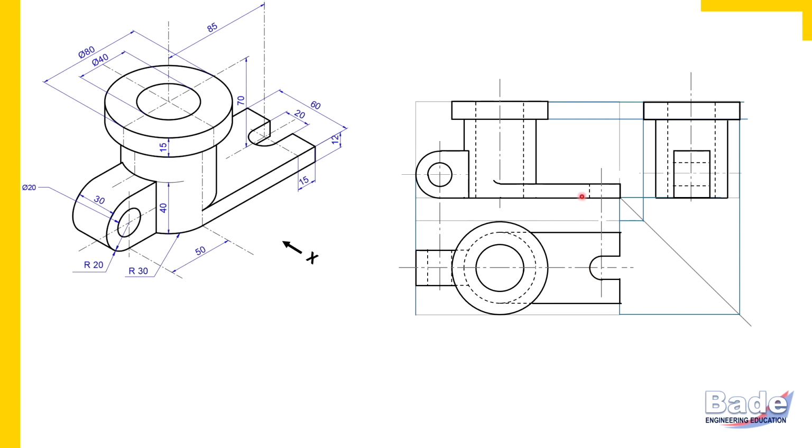Okay, now let's complete this plate in the side view. Which two dimensions do you get in the side view? Width horizontally and height vertically. So let's project height in the side view. Height of the plate is 12 millimeters. I have projected it in the side view. And width is 20 millimeters, which we have already measured here. Project. Width of the plate, right? Width of the plate is 60 millimeters. So I have projected it.